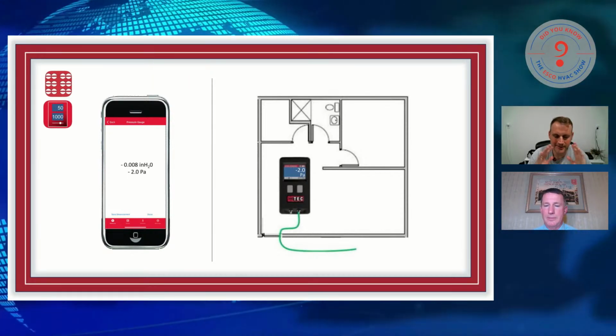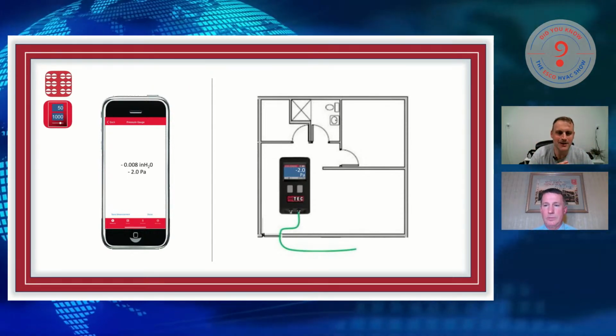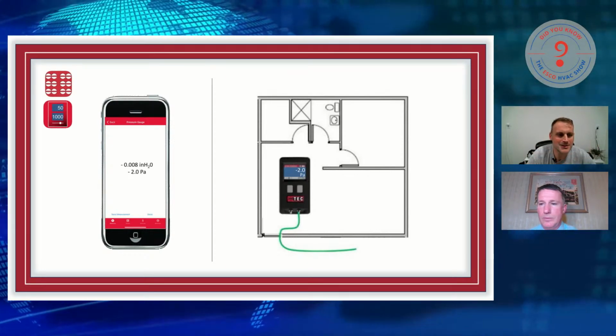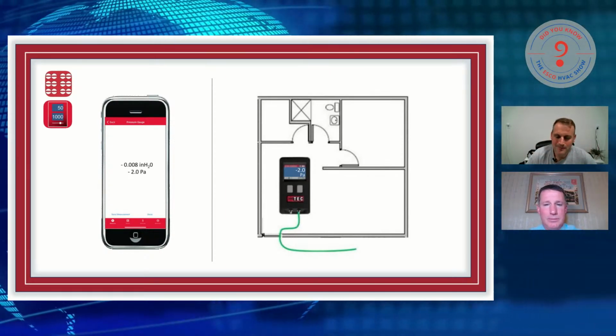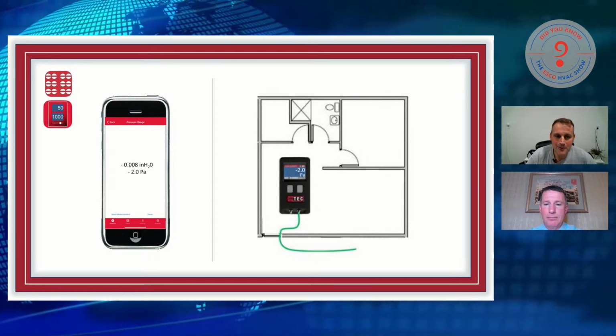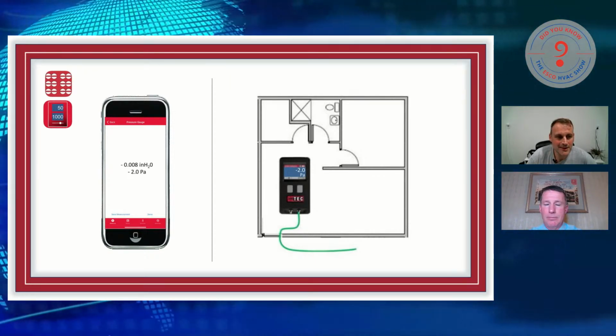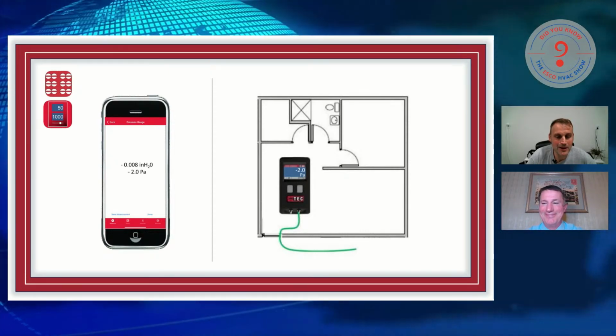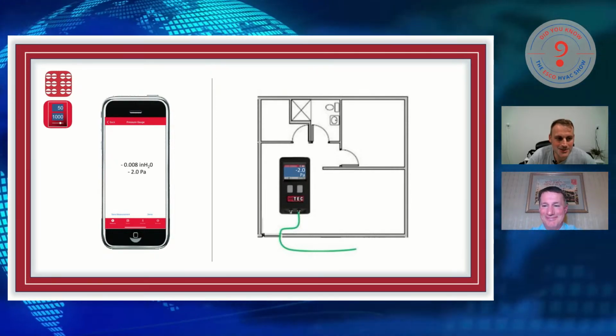Let's say the return is sealed up really good, a single box return, lots of supply ductwork, and the supply ductwork is leaking 200 CFM, a bunch of attic ductwork. You can run a tube outside the door on a non-windy day, and you can see that ductwork is leaking. We call that a dominant duct leakage test.